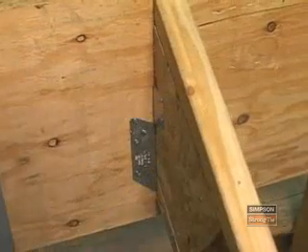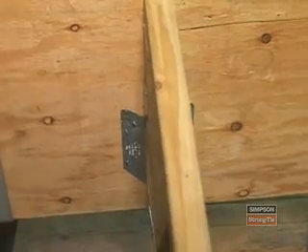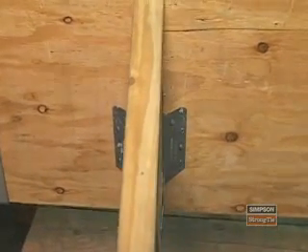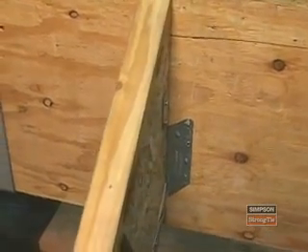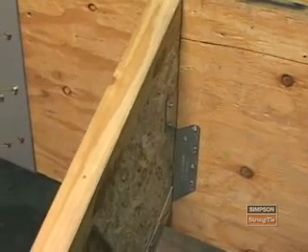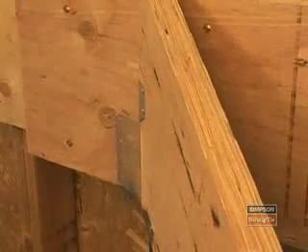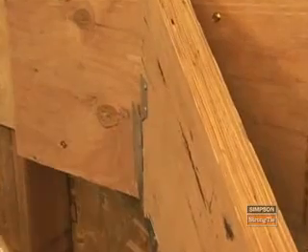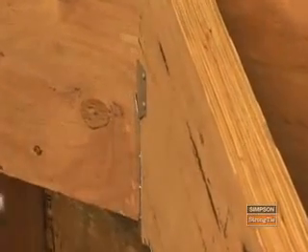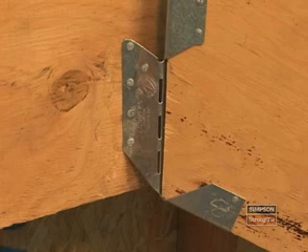If you are using the LSSU hanger for sloped rafters that are not skewed, neither header flange should be bent. Both header flanges should be flush against the header face. With any connector that is designed to be field bent, make sure that you bend it only once. Bending the steel back and forth can crack and weaken the steel. This could cause failure. Here is a correctly installed LSSU series hanger.